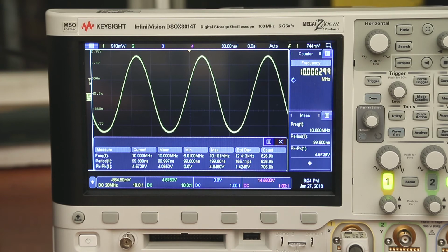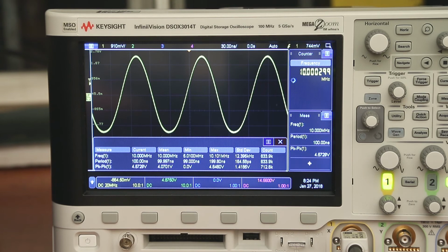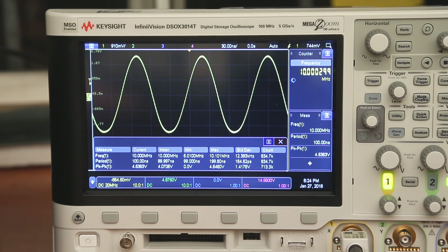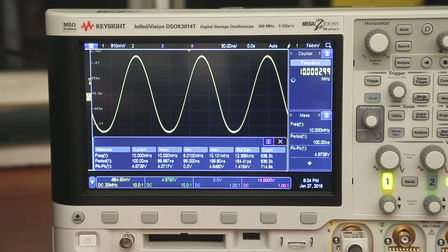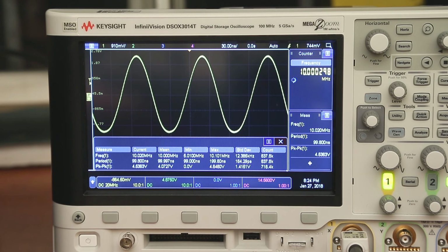It's just larger and clearer, and if you look at the way that the waveform is being displayed on the Keysight, it's very clean and very nice, but when you look at the screen, everything is grouped together, and by the time you've got the statistics on, and I was using this the other day, I was logging a PWM signal I was generating, which I was feeding into a MOSFET, and I wanted to see whether it was changing over time because of heat variations. I just found that the display on the RTB is easier, and the accuracy is almost as good as the Keysight. So from that point of view, there's very little difference.